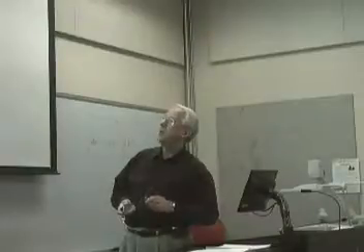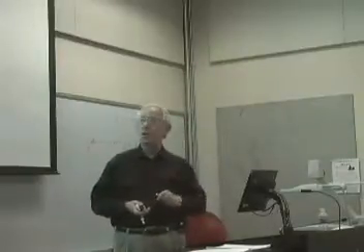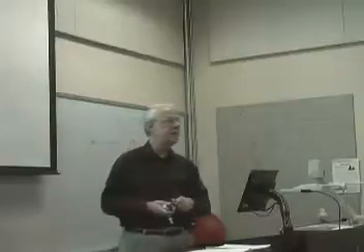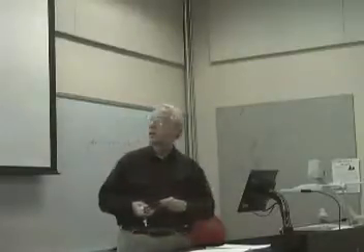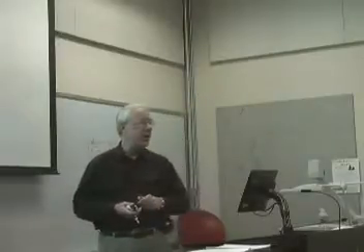This is what the polynomials would look like as far as the 3-node triangle. And then ultimately you can solve for those 3 unknowns. You can solve for the area of any triangle. By the way, this is a good little relation in case you ever run across a triangle in which you don't know what the area is. As long as you know these vertices, you can plug into that formula, it will give you the area.